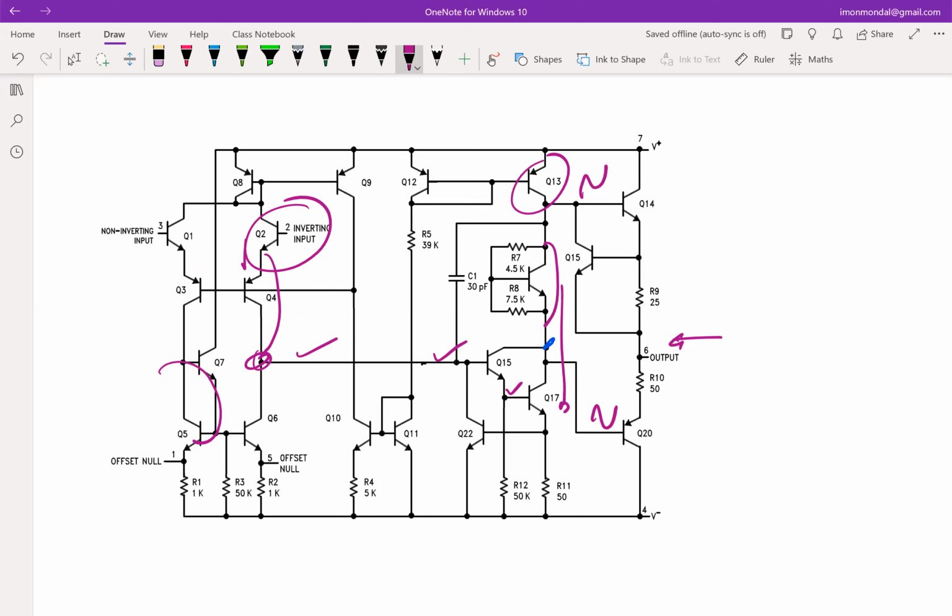You get an incremental current in case of a MOSFET if the looking-down impedance is 0 or low. So in this case, looking into the source is low, or the emitter is low. So the PNP gives you that flexibility. So you put a PNP there. It's essentially a current buffer, similar to that of a MOSFET. So that's how you go about doing it. Okay, so that is as far as the 741 is concerned.